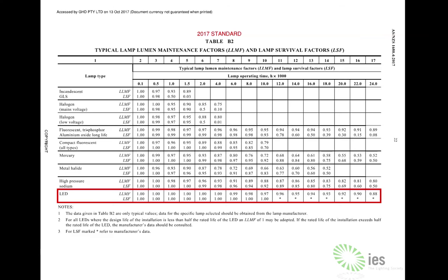It's really strict, and the reason for that is I wanted to fall back on the ability to compare A and B and say these two are not technically equivalent at any point. The 2000 lumens, the L70B50 50,000 hours versus the L90B10 100,000 hours, completely changes the thing. And as a result, I'm happy to use the L70B50 50,000 hours.